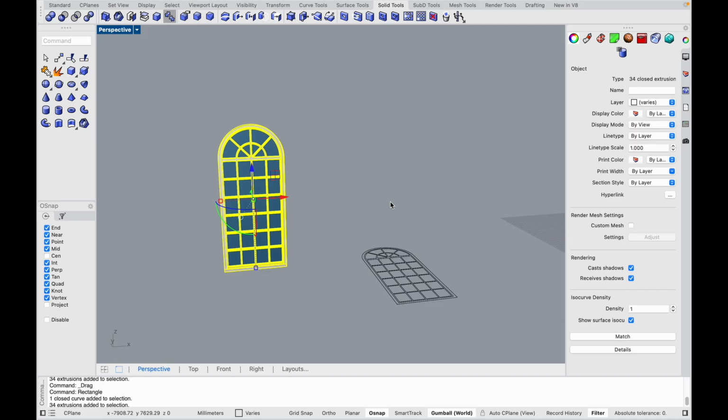But saying in a short way, if you have some objects which are repeated in your project a lot, for example, windows, columns, doors, so a lot of objects which are absolutely the same, it is very good and very clever to make them blocks. The main difference of a block from a group is that if you change one instance of a block, all other instances also change. So they are not independent. They are like relatives. They remember their relationships.